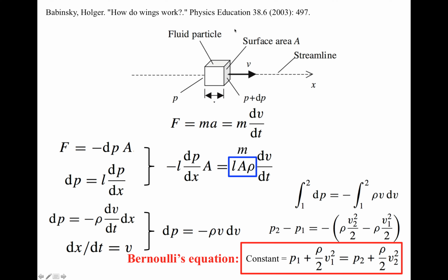For every position of the particle along the streamline, we can create a local coordinate system with its x direction lying in the direction of the local velocity that's tangent to the local streamline. So the same analysis still applies, and the result is still correct for curved streamlines.